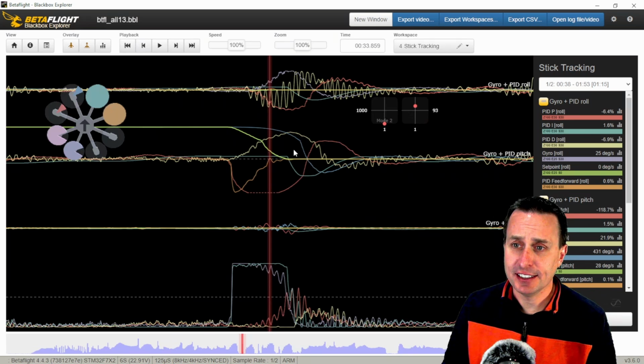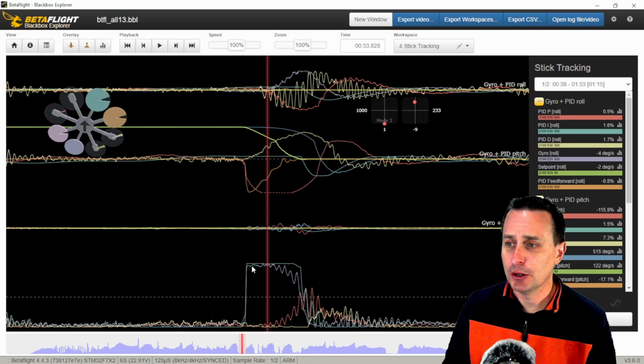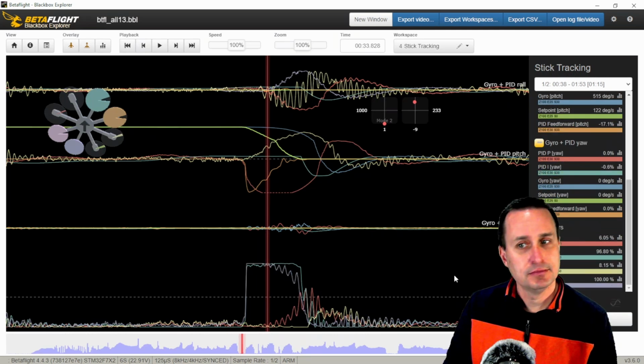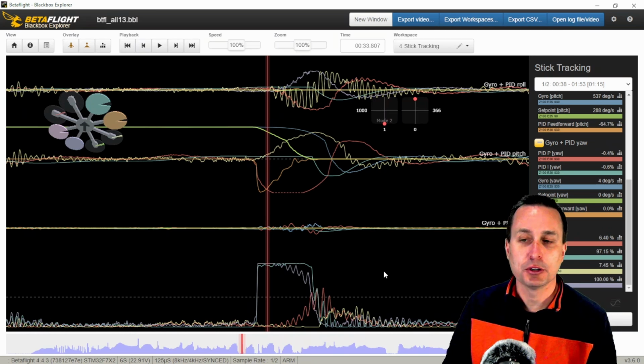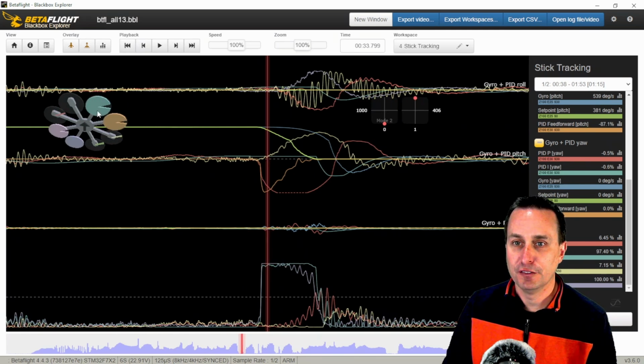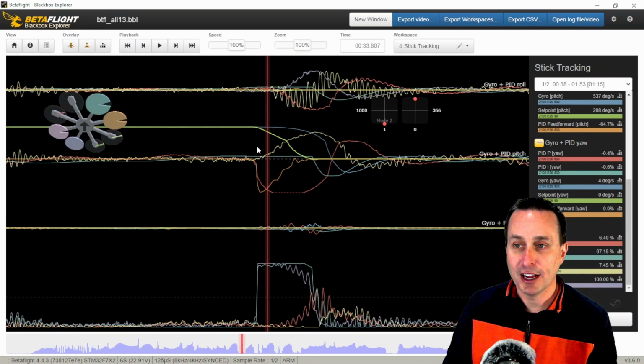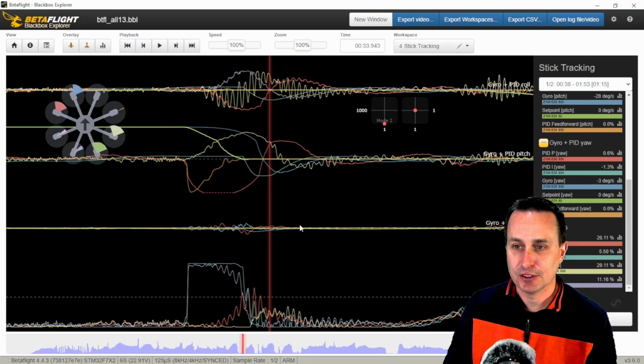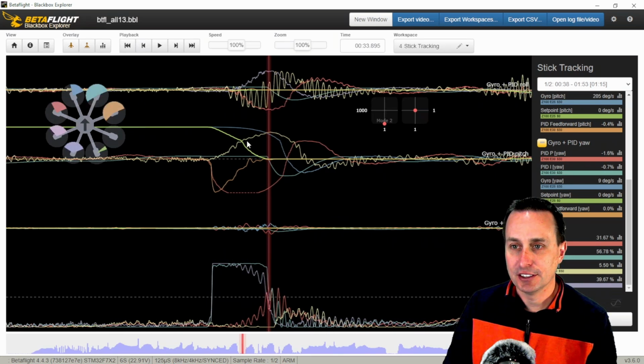Oh, and don't try to tighten this up with feed forward and all that jazz. It's not that. It's this right here. Look, you can see your motors are maxed out. It's just so heavy that you would need bigger motors to make this not so bad, this gap in between here. You're maxing out, it's calling 100% of 4 motors here. It's probably an octo stacked motors, but it's calling 4 of them to spin up to 100% to arrest this. It's giving all the chooch it's got, and it's just still not quite enough to close this gap.